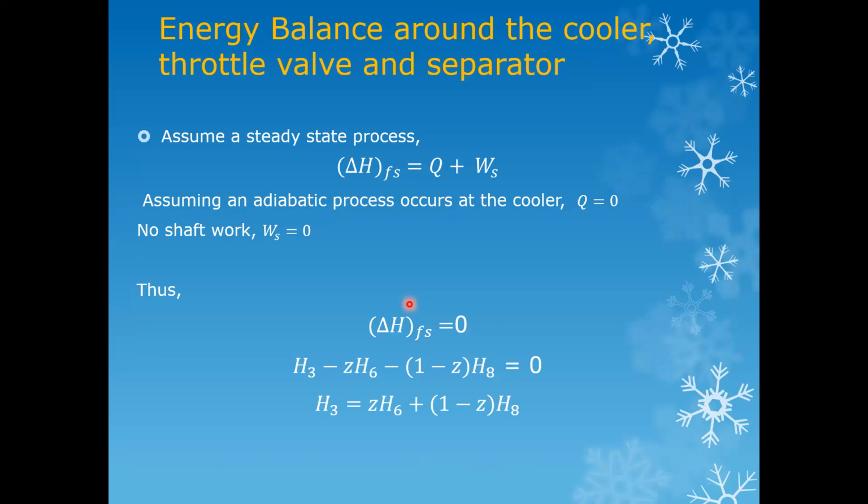Let's assume a steady state process and do an energy balance around the coolers, throttle valve, and separator. Assuming an adiabatic process and no shaft work, this is our energy balance.